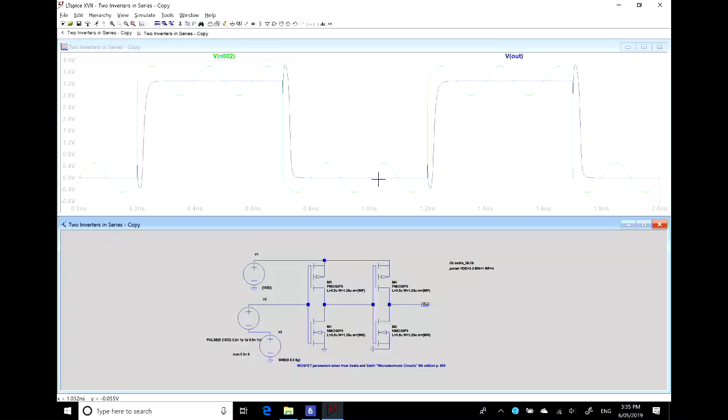You can play around at home with different amplitudes, etc. Of course, if the noise is too big, you're going to break it, but this noise was quite large already, and we get a very beautiful signal coming out. And there's no magic, there's no rounding off, there's no nothing. It's just that inverters have very high gain, and so you get a very flat response, very sharp response, very flat response. Any questions there? So this emphasises to you that digital systems are robust to noise.